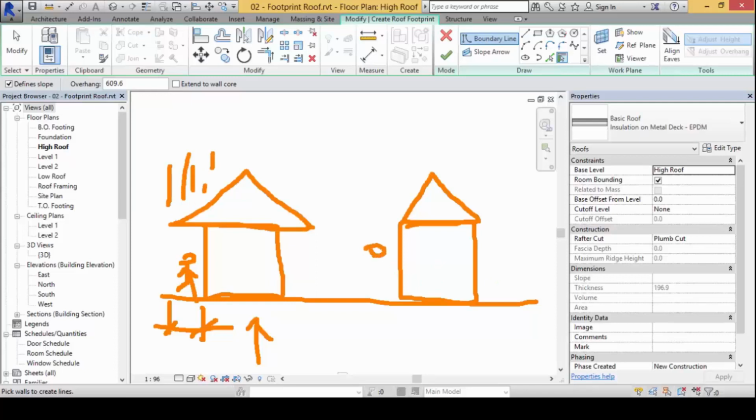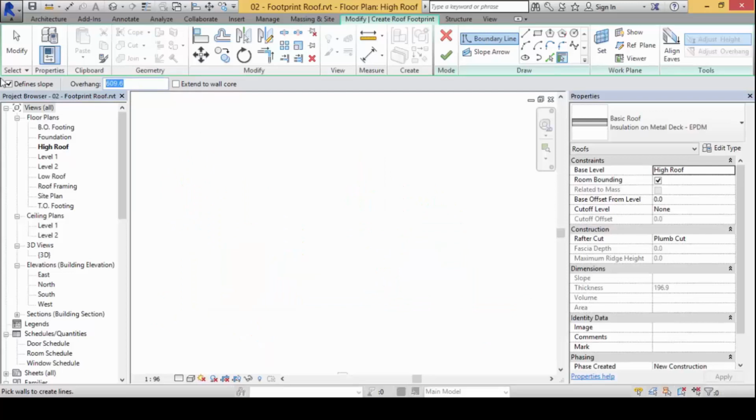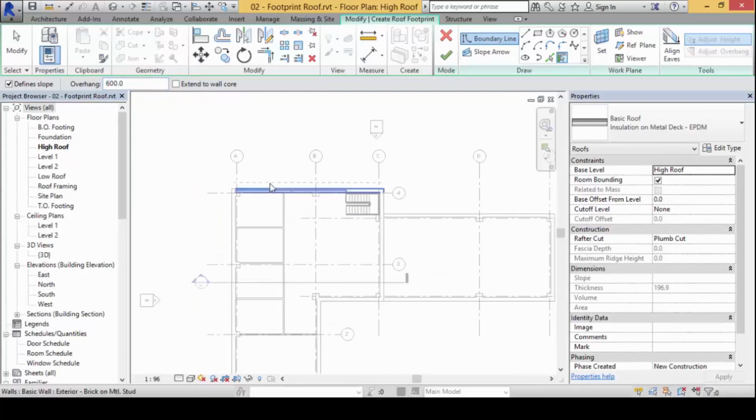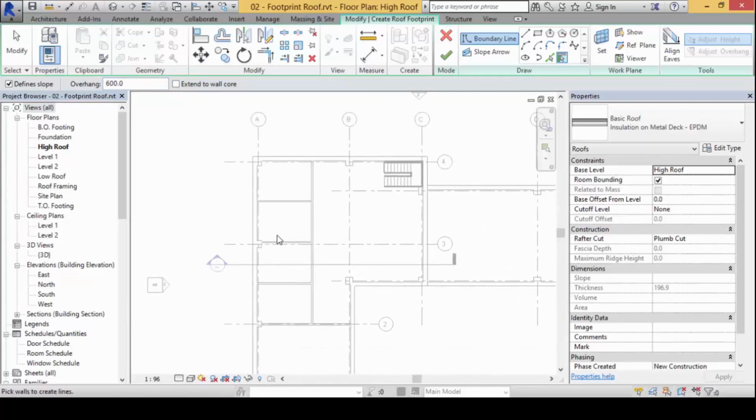Now, without the overhang, not that we cannot build this, we can. In a raining situation here, you're going to need an umbrella. That's the thing. Alright? So that's why overhang, that's what it means. Okay? Now with this, we're going to set the overhang at, let's say, 2 feet for now. Now with this, after we have set this, then we begin to draw. Okay? In this case, we don't draw still, we use the pick walls function.